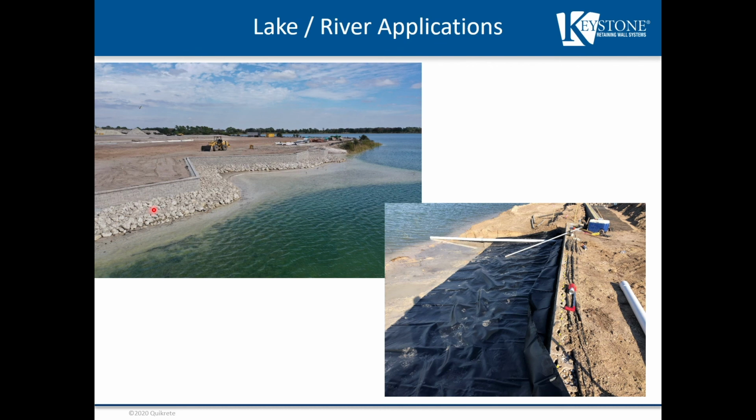So we're going to put in some type of filter fabric at the face to protect that surrounding subgrade. We're going to put in our wave action material or riprap or boulders or some other type of material to protect that, or even hard armor like a concrete revetment system.